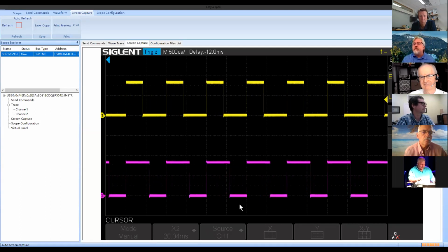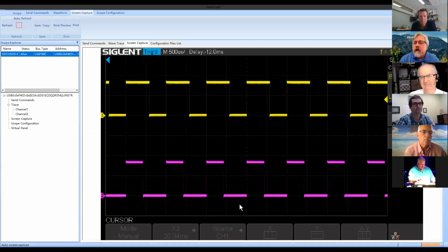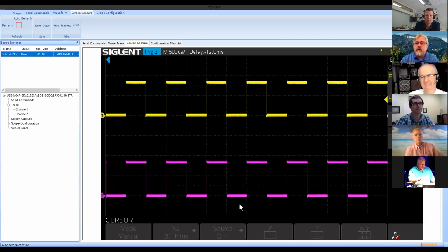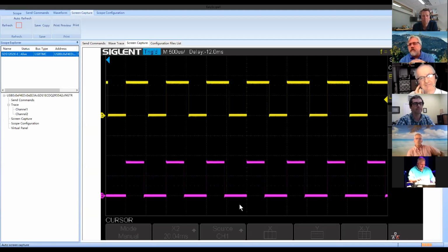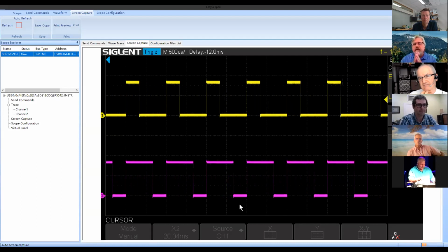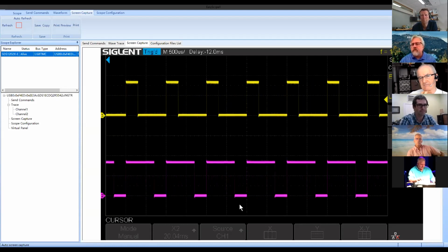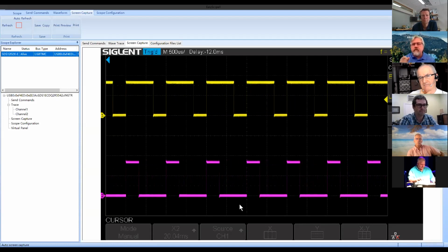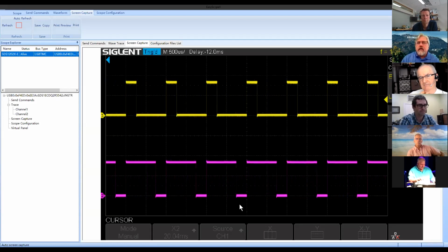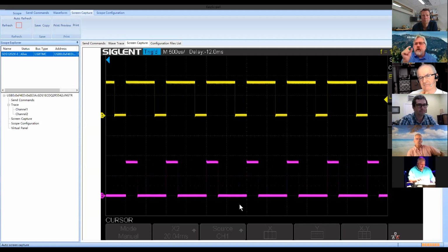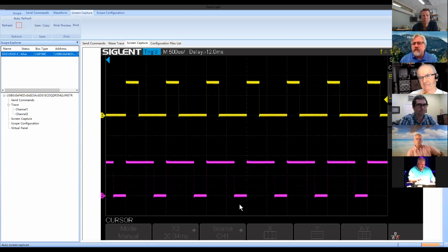Now, in some cases, people don't like to do that. So there is another mode in PWM. Now, I'm using sawtooth mode for this. There is a triangle mode that will allow you to offset. It's a little tricky to explain without having a lot of graphics, but for motor controllers, some people prefer that. Now, when you're doing your setup, you have to know if you're using triangle mode and you have to change your X configuration a little bit.